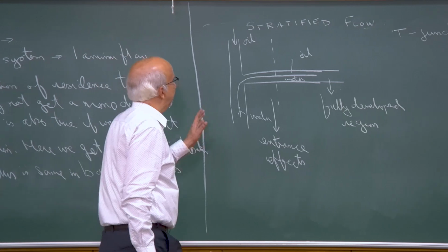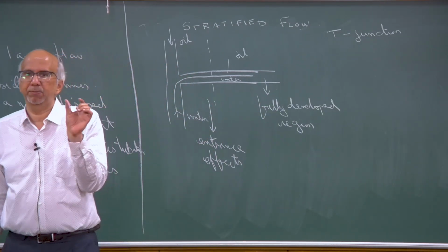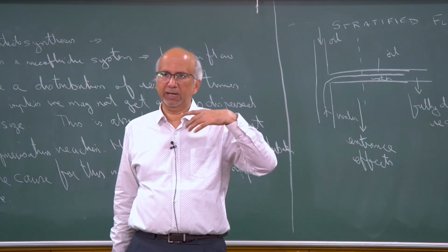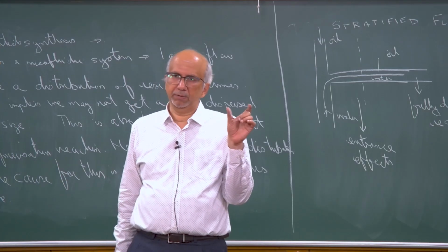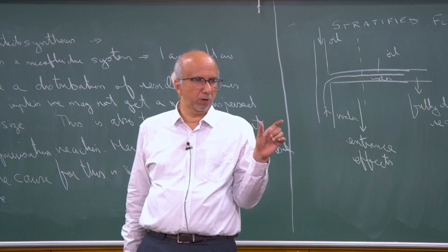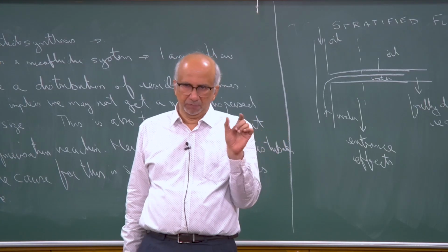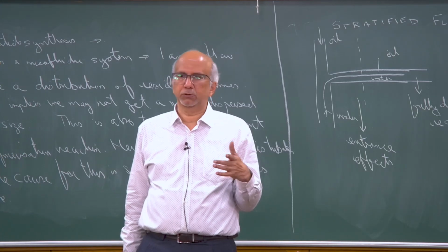Now, in an actual system, the entrance region may be very small compared to the full length. So, if you are carrying out a reaction or an extraction or something, the main process is going to happen only in the fully developed region. In the entrance region, which is a very small region, you can neglect it.